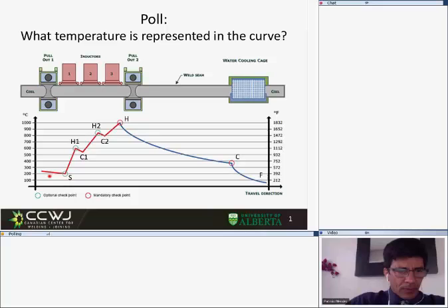And below, we have this other schematic of temperature as a function of the distance. We have the starting temperature coming out of welding, and it's hot, and then it cools down a bit, and it's hot after a second inductor, then we reach a peak temperature and it cools down until it reaches the quenching cage.